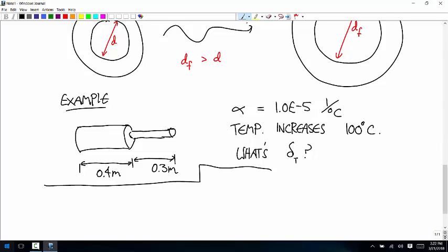Another interesting application here, I think, is if you put a test tube over a Bunsen burner or something, what makes the glass crack? Well, if the whole thing was heated up exactly uniformly, there'd be no problem. The whole thing would steadily increase in size, and no issue. But if you have the fire right under one corner, that one corner is heating up a lot faster than the other stuff.